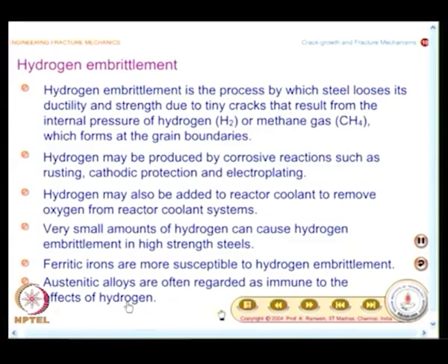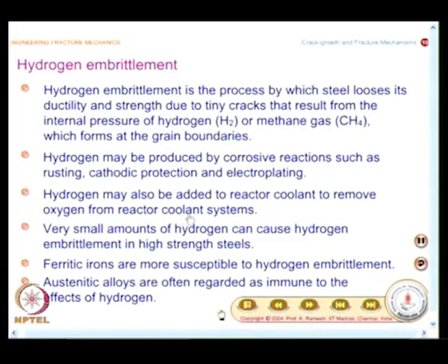In fact, an observation like this is advantageous, because if you know your corrosive environment, there is a possibility of crack growth by active path dissolution, then use an appropriate quality of steel. On the other hand, if you are going to have predominantly hydrogen embrittlement, go for austenitic steels. So, you have a via media by selecting an appropriate material for your structure, you are able to overcome or minimize such problems. I suppose you had time to take down the points that are listed,